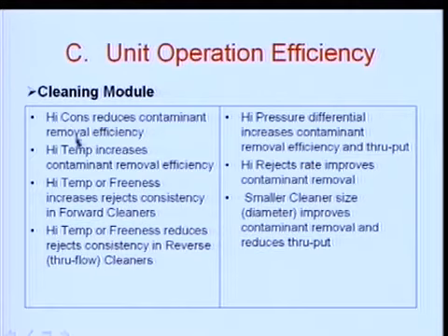Cleaning module, same principles apply that you've just seen in the screening module. High consistency reduces contaminant removal. High temperature increases contaminant removal. Now this is opposite to the screens. In the screens, high temperature reduces contaminant removal, especially for the pliable and malleable contamination, as you saw, but high temperature increases contaminant removal efficiency in a cleaner, because this is dependent on specific gravity and viscosity, and as the temperature increases, viscosity decreases.